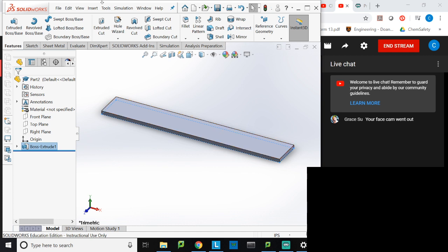So what I'm going to do to make this work is create little circular brackets that are going to mount to the threaded rods. They're going to have a threaded hole cut in them so that the threaded rod screws in, and when the threaded rod turns, it causes it to move up and down. That's how a lot of 3D printers work.